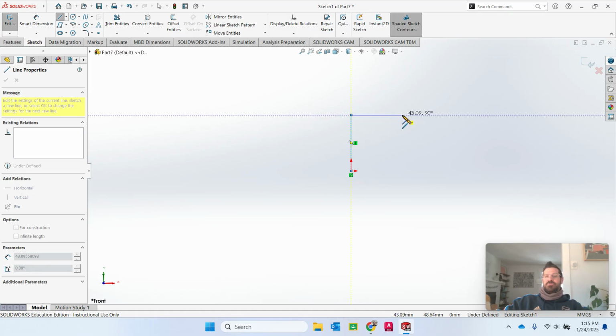And you're going to say, I'm just drawing a line. I drew that first line as vertical, and you can see on my screen right there, there's a little green box with a vertical line on it. That means that one of the geometric constraints it placed on that says it expects that line is going to stay vertical. If you don't want it to be that, you can change it, but let's just say I want it to be like that for now.